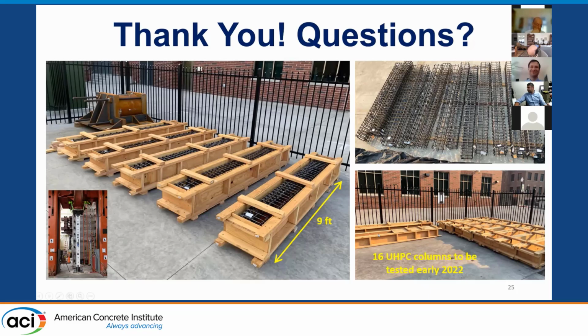Oh, that's an excellent question. So far, most of the UHPC products that we have used for the structural components are proprietary mixes in the range of 22 to 25 KSI, maybe 20 to 25 KSI. But we are doing some work on non-proprietary UHPCs that are on the lower end, maybe 15, or maybe not 15, maybe 18 KSI, but we don't have a recommendation for this lower range yet. So to answer your question, this is mostly for 20, 22-ish KSI UHPCs. And then we will see if the same is valid for lower end types of UHPCs.